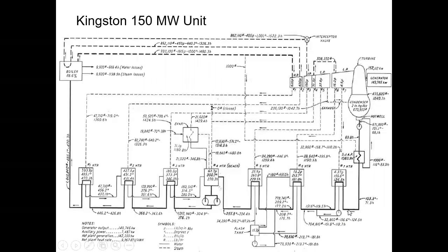But you see, coming out of this open feed water heater, I have to have pumps. Now, these are closed heat exchangers. So this is a big pipe and it comes up and then the water goes through tubes and steam is condensing on the outside, et cetera. And so all of this is enclosed in tubes all the way to the boiler, okay?